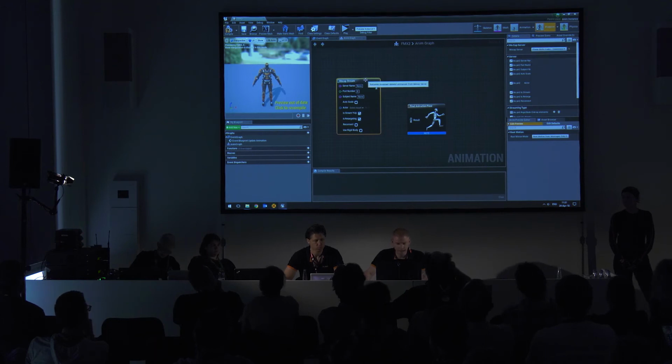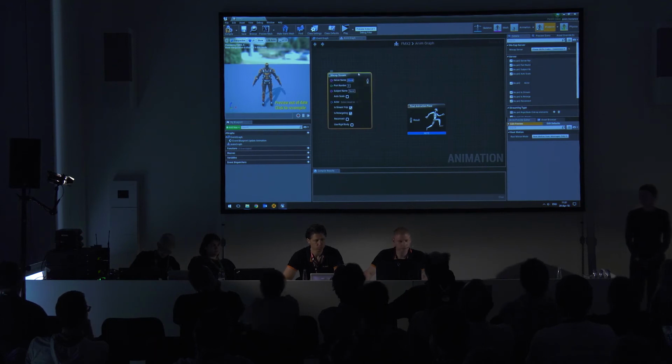Once I've selected that, I need to do pretty much the same as what I did when I imported the skeleton. So the server name, again, 00.0, port number 802. Subject name, again, I'm going to set that to 1. Deselect Y is up because we have Z is up. Is retargeting, yes, and I'd like to reconnect this.